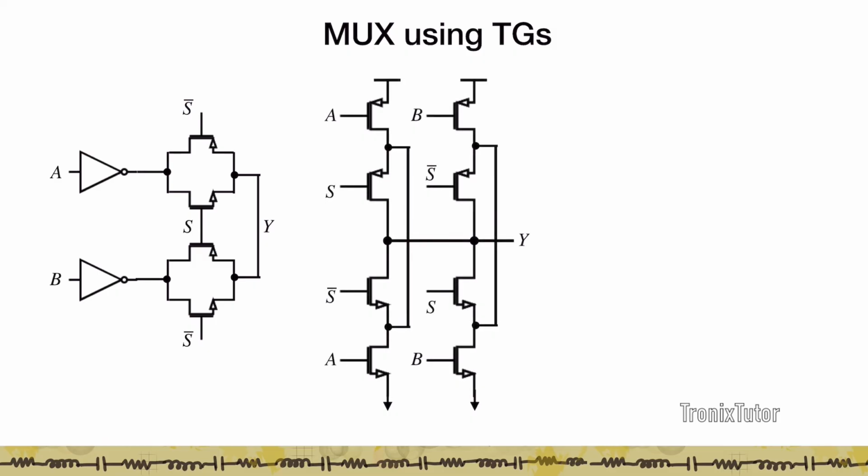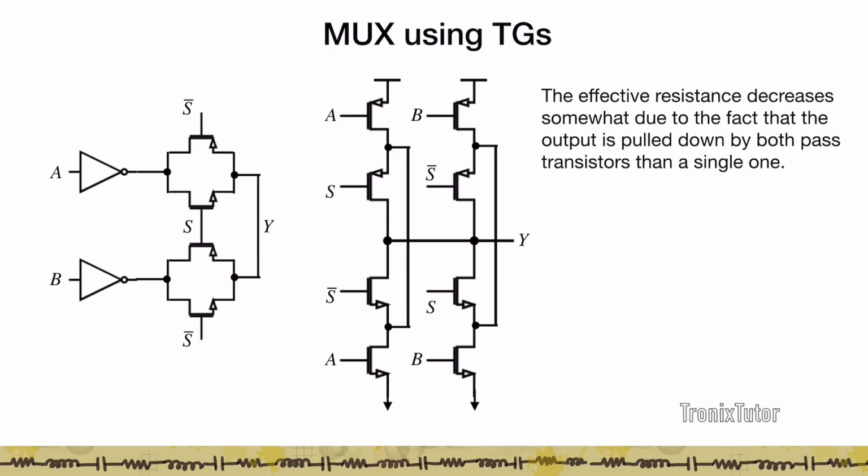And so to design or to time the circuit, I will open up the inverter, open up the transmission gates, and basically what I see is a circuit which looks like this. And so now if I want to look at the timing of the circuit, you see that this circuit looks like a CMOS circuit except for these two connections. Now these two connections actually are going to help with both the pull up and pull down, because they essentially represent the parallel paths that this transmission gate is giving.